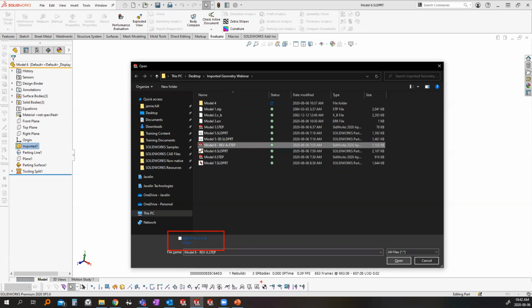So if I had a sketch with a line in it, it would be line 1 at sketch 1 at feature 1 at part 1, essentially the internal ID that it goes by. And if I don't hit this check mark, all of those faces and internal IDs, entities, sketches, everything gets swapped out for something new.